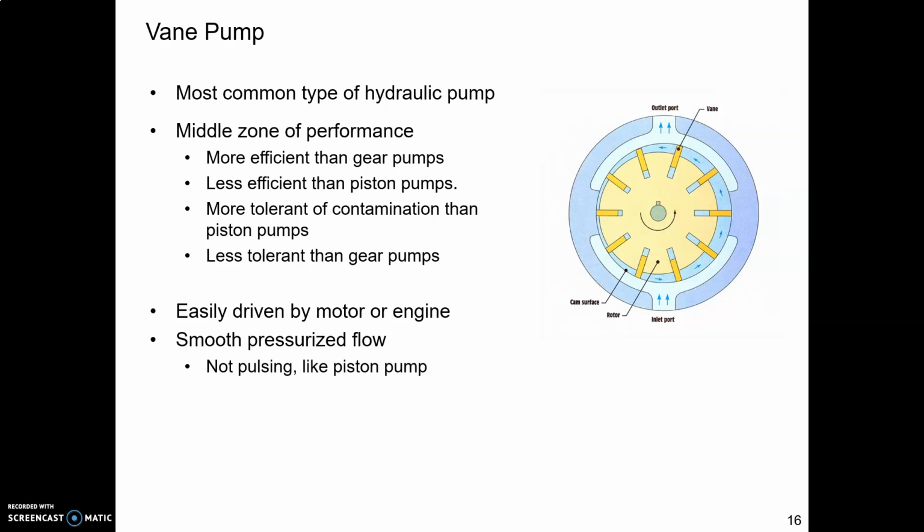Probably the most common type of pump in hydraulic systems is a Vane Pump. So this is in the middle of the spectrum, middle cost, middle noise, middle capacity, middle efficiency. And as it goes around, the centrifugal force, I know that's not a real thing, you physics people, centrifugal force pulls those vanes outward until they seal against the body,